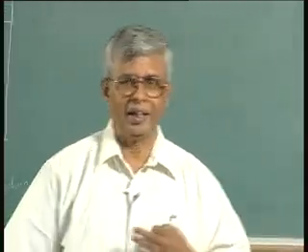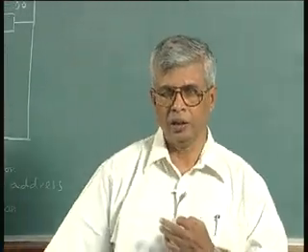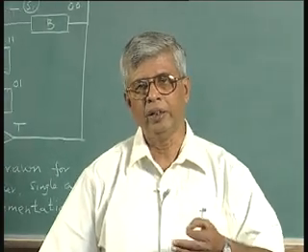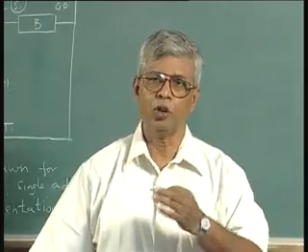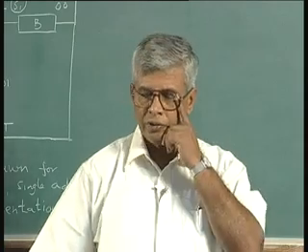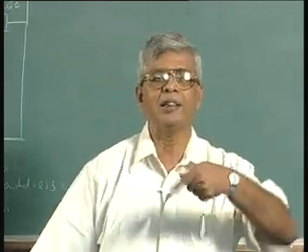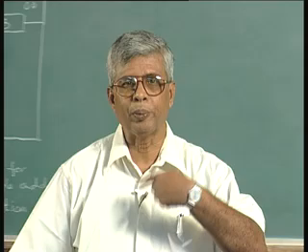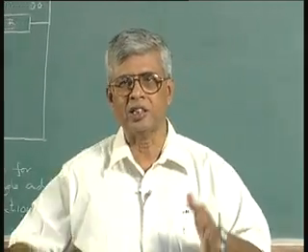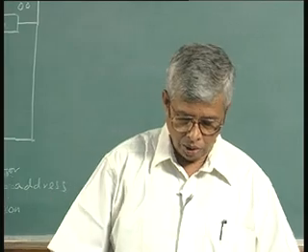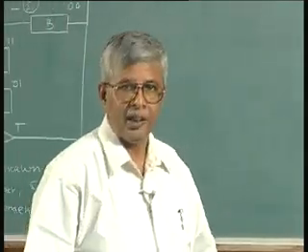And for the other test, the result of the qualifier being different, then instead of going to 001, it will go to some other state. So, I do not have to keep writing the next state, which is an increment of the present state. I can drop that from my table, and to that extent I can shrink the size of the ROM. This is where we stopped in the last lecture.